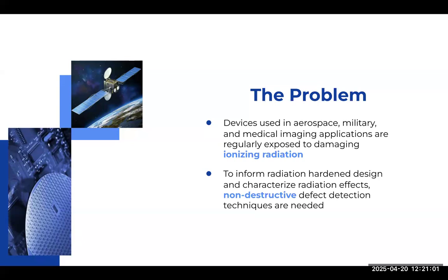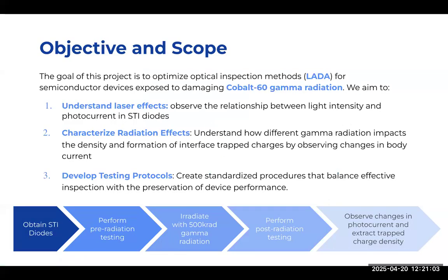during fault detection. The goal of this project is to optimize inspection methods for semiconductor devices exposed to damaging cobalt-60 gamma radiation through understanding laser effects, characterizing radiation effects, and developing testing protocols. IV sweeps of STI diodes were performed pre and post gamma ray exposure to measure damaging effects.